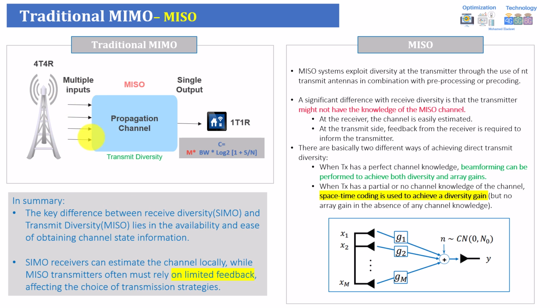It will utilize all the antenna elements to make a more directive beam towards the user, which is usually called array gain, by focusing the signal toward this particular receiver. And this is usually called maximum ratio transmission. The last one was called maximum ratio receiver, and this one is called maximum ratio transmission. So this is the first part. If it receives channel feedback, it will generate this antenna array gain, which means you will have a more directive signal towards the user to improve the signal quality.